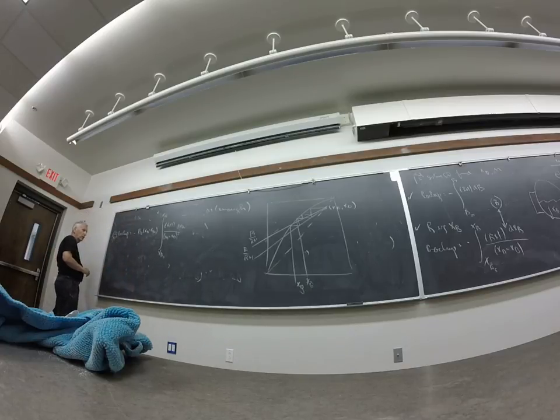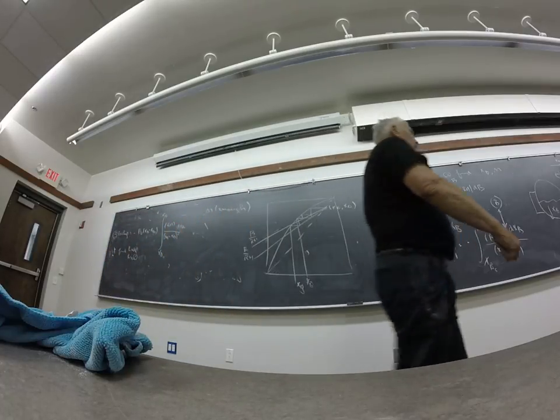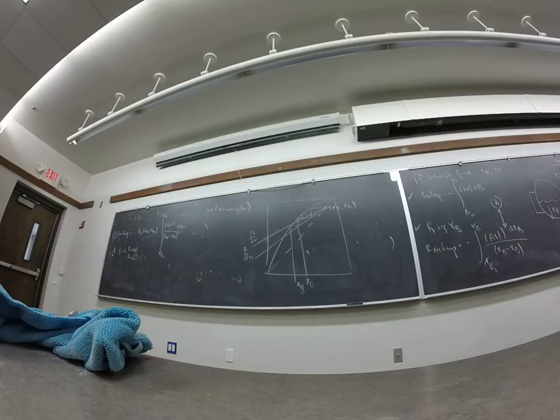Now, one of the things a person might do is he might say, set the boil-ups equal. No. First thing you might do, most obvious thing to do, is just calculate the boil-ups. Find boil-up 1 and boil-up 2, and take the one with the least boil-up. It'll cost you the least heat. So that would make your choice for you.